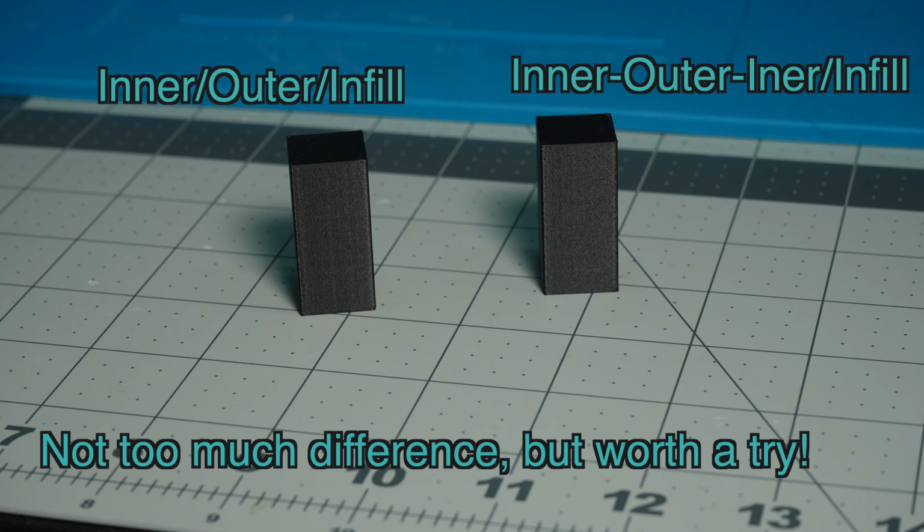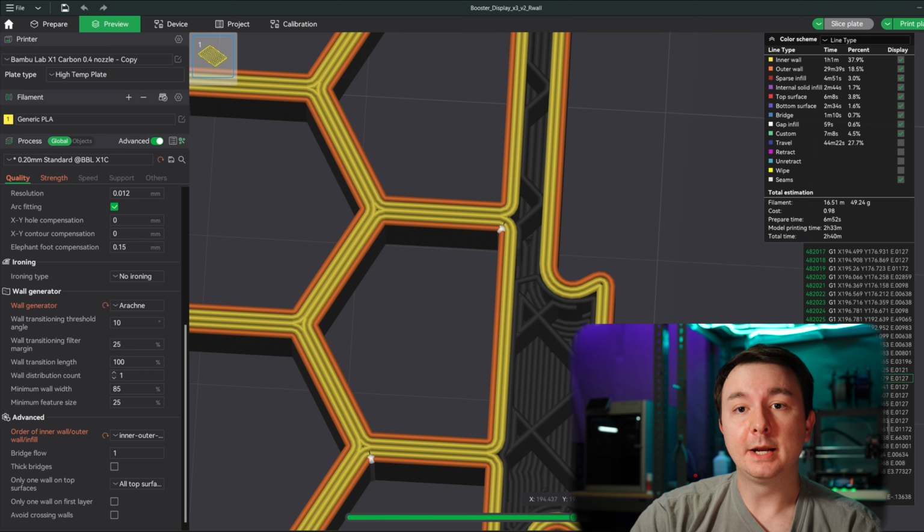Then, without the error stacking of all of those perimeters stacked together, it'll print the outside and then squish the middle one in. And theoretically, your outermost perimeter should be cooled at that point, and you shouldn't see as much error. This is a good choice, and if you're not using it, I definitely recommend trying it out and seeing if it helps.